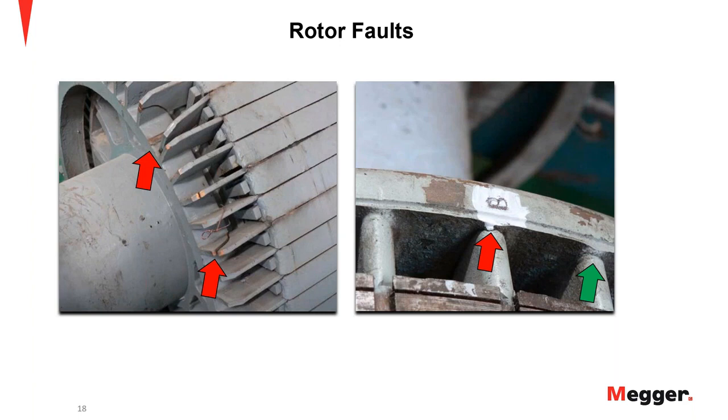The fins seem to have started moving also, because you can see that this one is bent a little bit, so it could have moved due to the centrifugal force of the rotor moving itself. There are a lot of things that could go wrong, and this could also hamper the rotor from turning smoothly inside the stator winding.